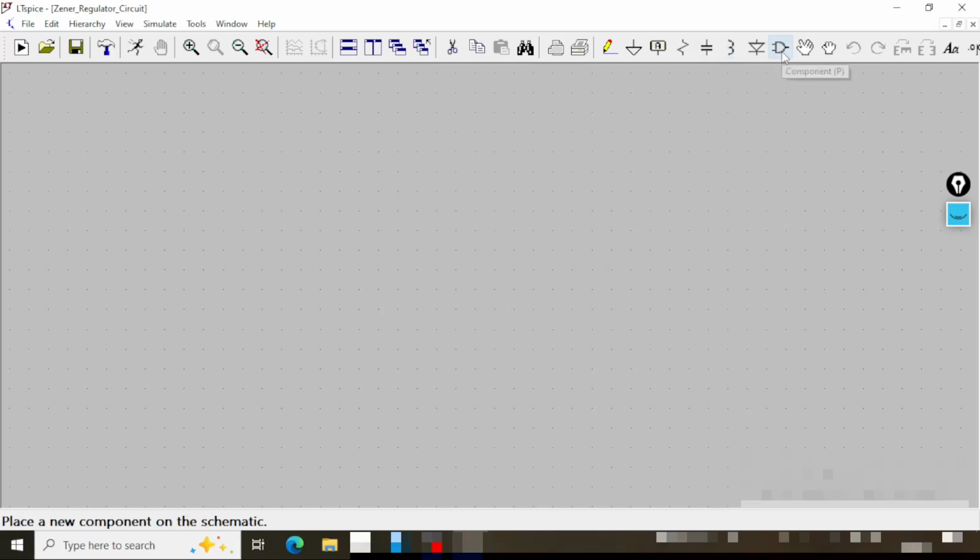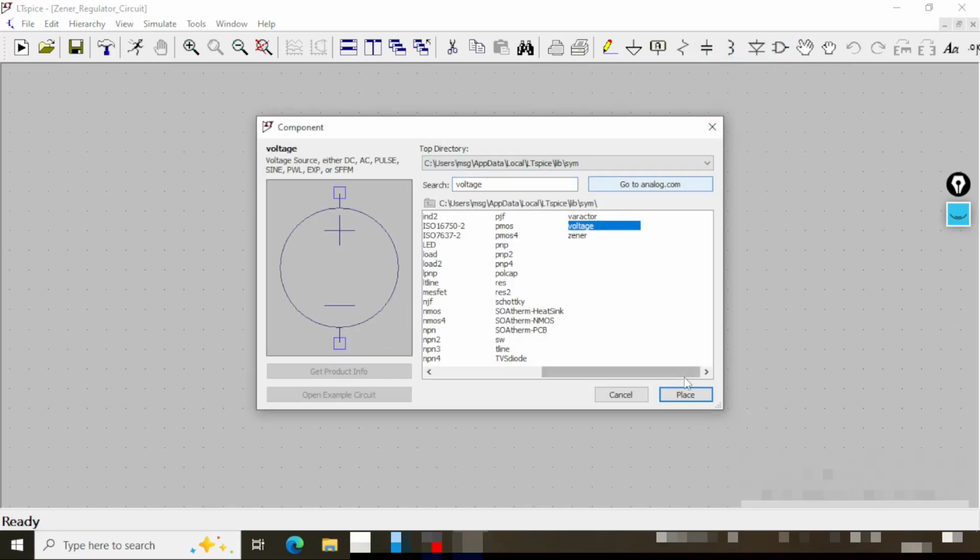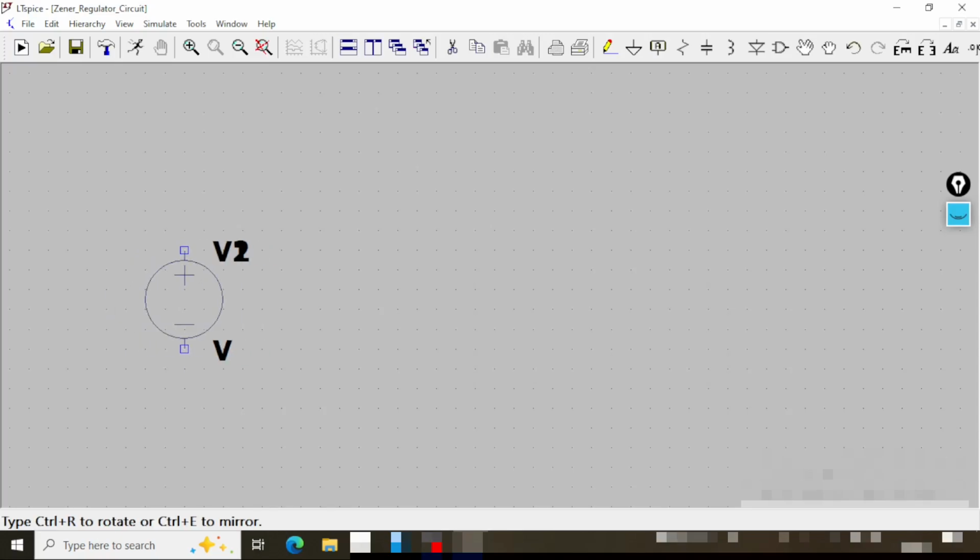First, I type and we have the voltage. So let me click it. Here is the voltage. We will not be needing any more voltage, so I right click and vanish it. Now we need 2 resistors, one in series, one as load. First let me hit Ctrl R, so it will act as a series resistor, and let me do the R again, and this will act as a load resistor. I don't need any more resistors, so I'll right click. Let me go to the save button and save the circuit.